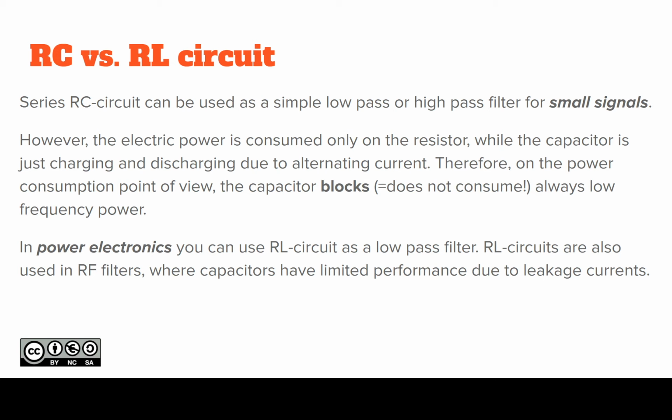Another place where the RL circuits are used is in radio frequency filters. In radio frequency, capacitors have limited performance due to leakage currents and such, and you cannot use active filters there, so in RF technology you use RL filters or RLC filters.